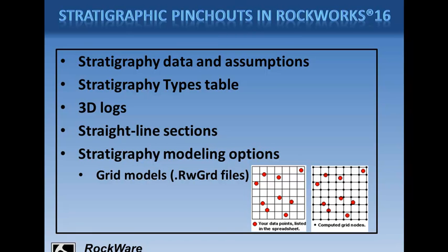Just as a reminder, you can imagine a grid model as a grid of imaginary lines that overlays your source data points. During gridding, the program assigns a value to the grid line intersections, which are called grid nodes, given the data at hand. In the case of stratigraphy models, the node values represent elevations for that surface, and the data it uses is pulled from the boreholes, shown here in red.